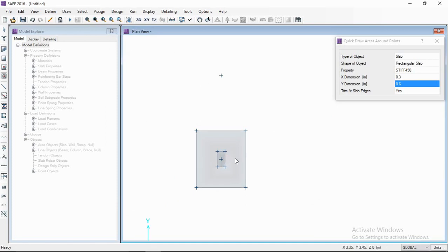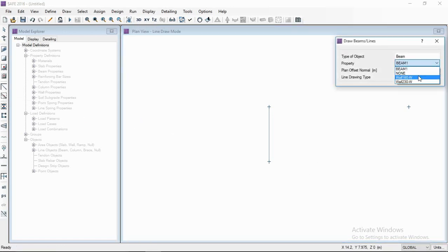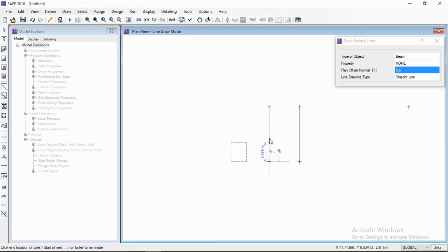So in this way, you have to draw all these points. For shear wall, you have to draw. Let's draw this for this shear wall so that you can understand. For this, I'm taking the beam line, a null line. I'm taking offset of 600. So take a 600 option and draw a line.